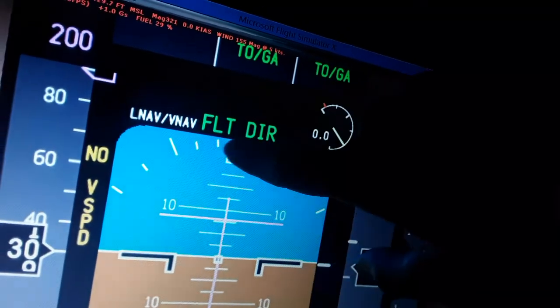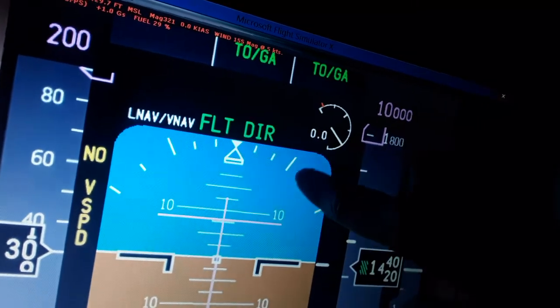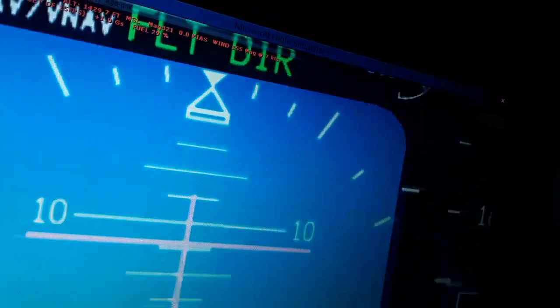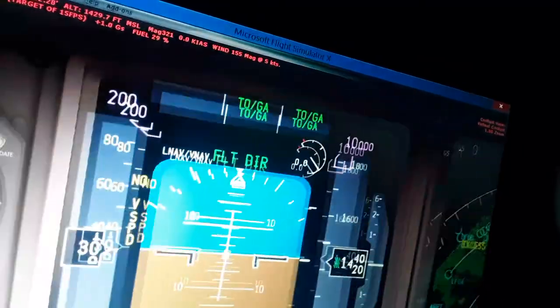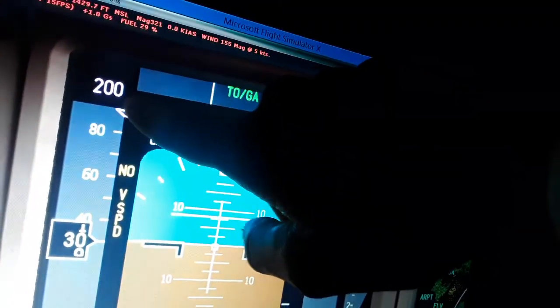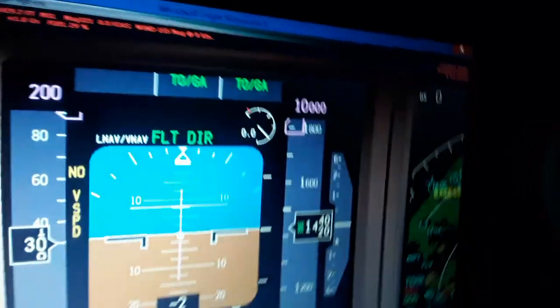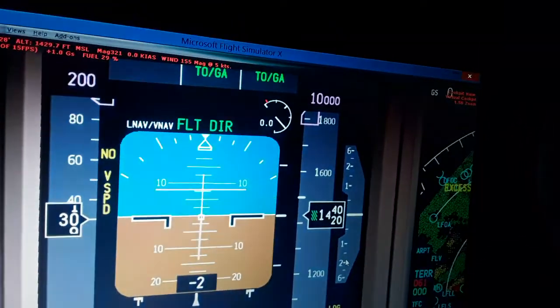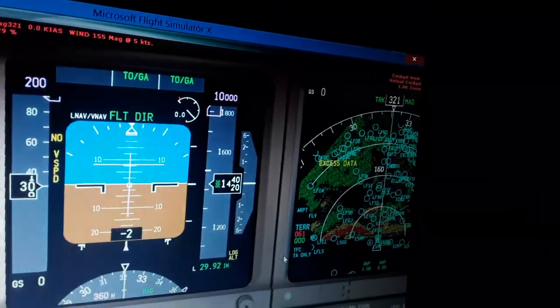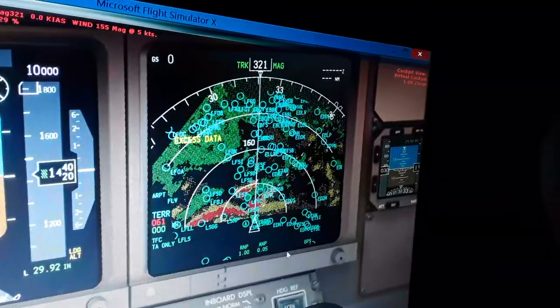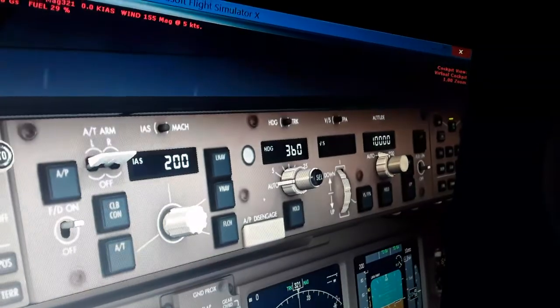You can see also in the bank angle, we have similar degrees limit. We have the angle of attack of the aircraft. We have the airspeed select and the altitude select from the autopilot flight director system. The flight mode annunciator with the auto throttle and the vertical and the horizontal navigation.